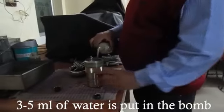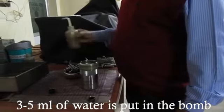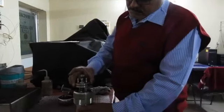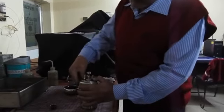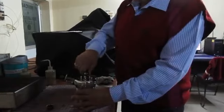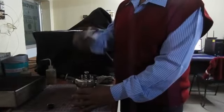The water will absorb the gases released post-combustion. If cotton thread is used for firing, it must touch the coal sample. The bomb is then assembled and it is ensured that the oxygen release valve is tight.